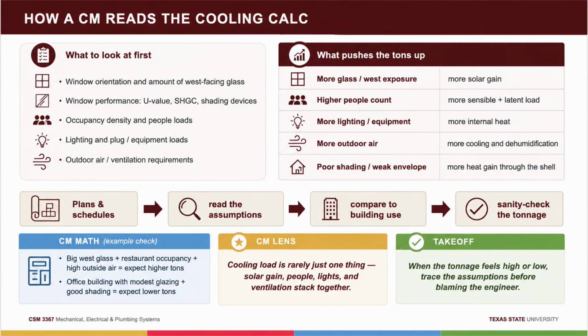So how does the industry make sure sizing is done right instead of by gut? Recognize calculation procedures, and two names to know. Manual J, the ACCA load calculation method for residential work. It's what a code official asks for when a home builder wants a permit for the HVAC. And for commercial buildings, Manual N and the ASHRAE methods, the CLTD approach we touched on earlier, and, in modern practice, hour-by-hour computer simulation that models the building through the whole design day.